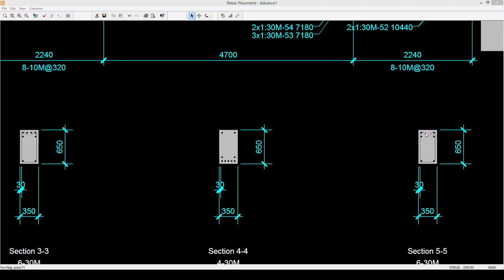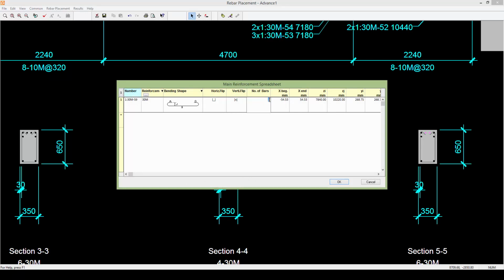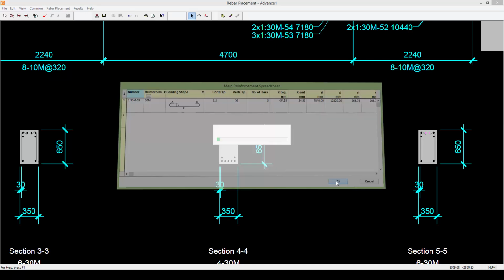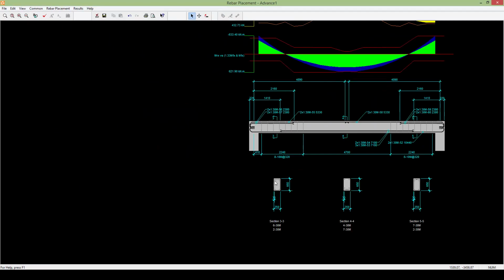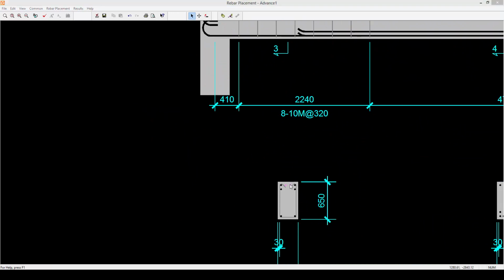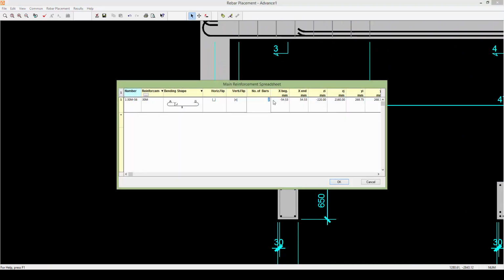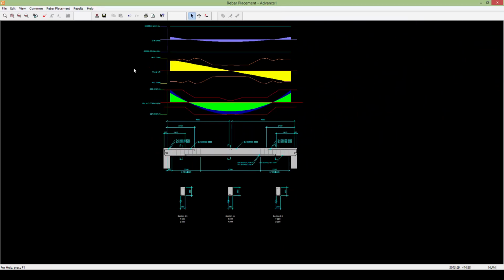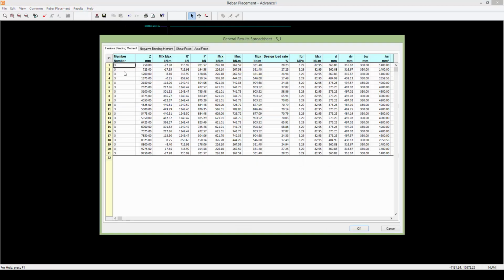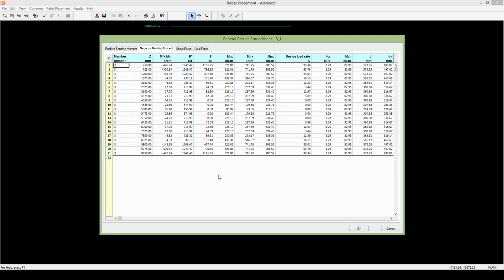So here, instead of 2, we can change it to 3. So as you see, it's here almost, and for this side also. So it's okay. And right now, if I check the results again, you cannot see those yellow rows because the beam right now it's okay. And it's on 95% design rate.